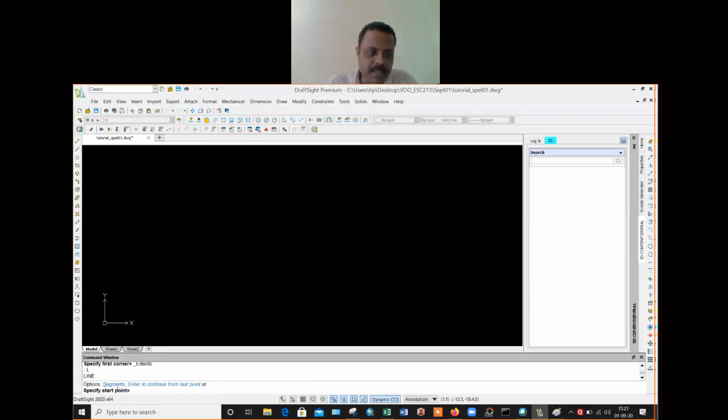Specify start point. Where is my start point? Zero, zero. So click here and then write 0 comma 0. Can you see it on the screen? Then enter.